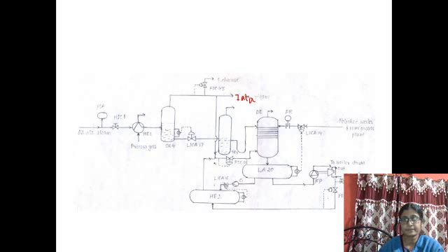That's why another pressure control loop exists, in order to check the pressure of the flow line. So what are the steps? From this separator unit, the 7 atm steam line is generated, and that steam line is used at the lower portion of the deaerator tank.